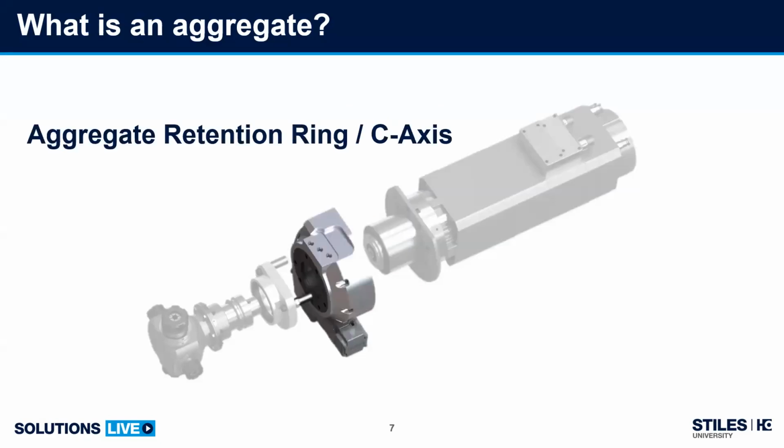And how that fits would be an aggregate retention ring or C-axis. So this highlighted portion that we see here would actually be a C-axis, which allows us to rotate in that C-axis. But that would slip over the nose of your spindle motor. As you can see there, that essentially would marry up with our spindle motor at that point. Looking at the inner dimension inside of that C-axis, you can see the black ring portion there. That would be considered our aggregate retention ring.